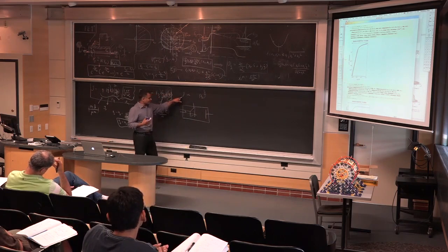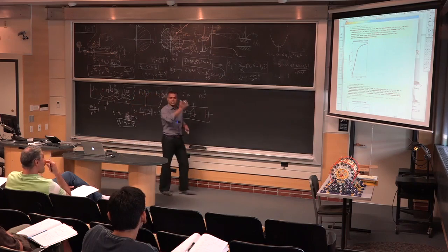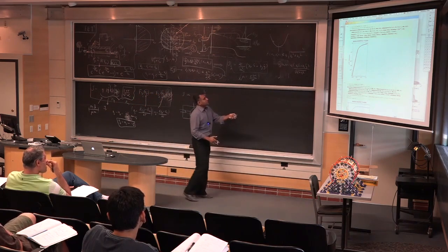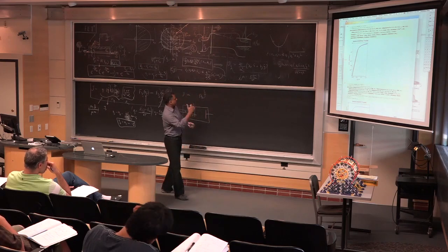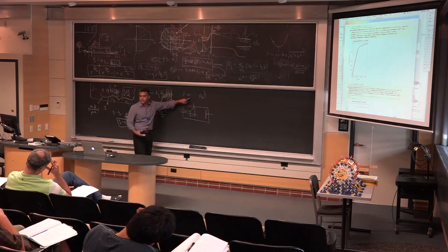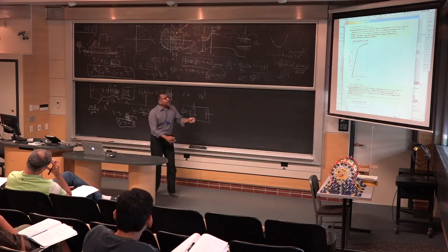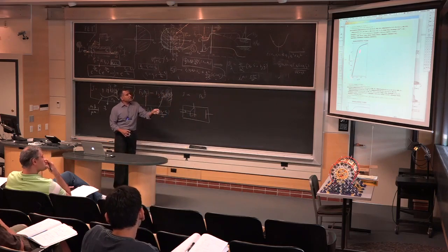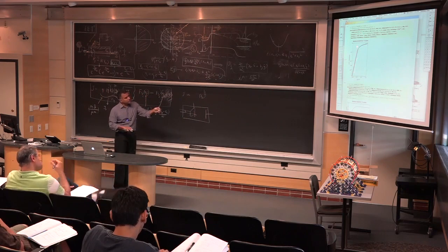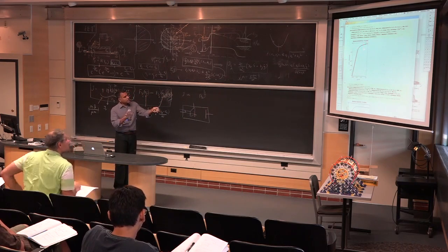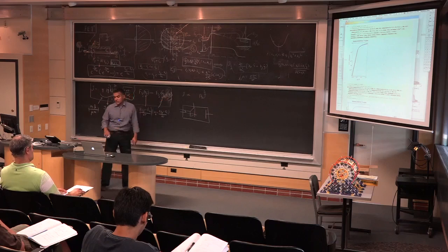And it's very amazing because it turns out that in a vacuum tube, you really have a ballistic situation. It's vacuum, there's nothing to scatter, right? I mean, it goes back to the same situation. In a ballistic transistor, the current, when you plot it in the linear scale out here, goes as a similar expression as the vacuum tube. We have taken away all the atoms. If there's no scattering, then really the atoms are not playing a role anymore. So it goes back there. Right? So that's a function of the gate voltage. Very sharp off, and when you turn on, it slows down and goes something like that.